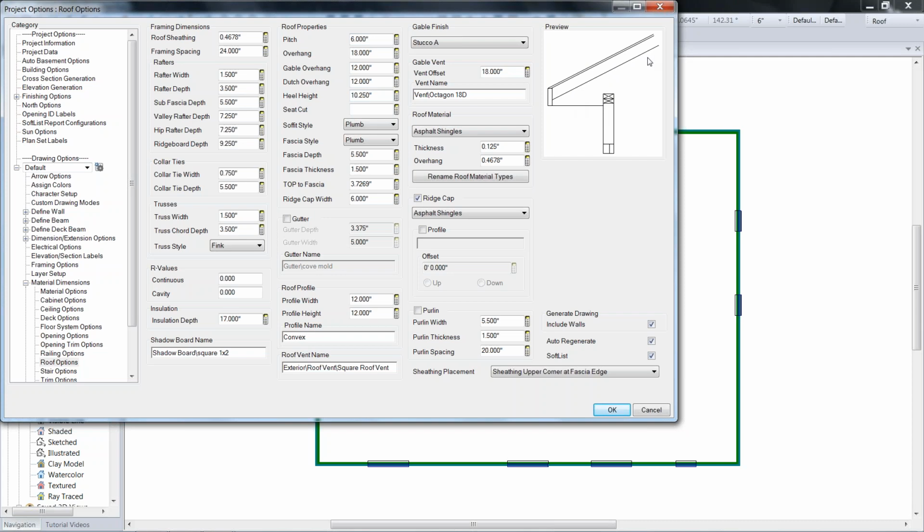So you're looking at the diagram before you finish. You'll notice that whether it's a rafter or a truss, we're missing that bottom chord for the truss system. But what matters is what's happening with that top chord and with the heel height. And that's all measured, by the way. The heel height is measured from the outside edge of that top plate all the way straight up to the top edge of that chord of the truss. Okay, so that's in place. So I say okay to that.